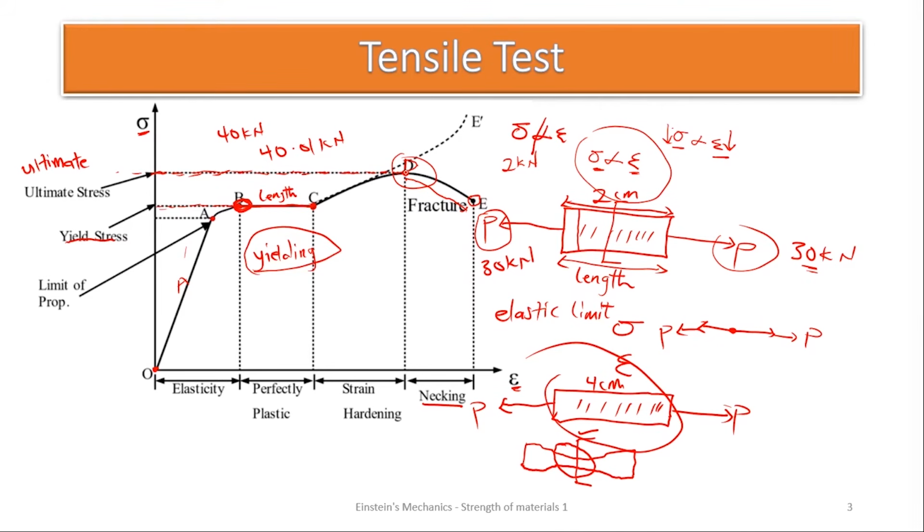Because when we read the ultimate stress, we were supposed to stop. We shouldn't have applied any other load. If it was 40, that was the strength of the material, the ultimate strength. But I decided to add a 0.1 kilonewton force to it. Then the material will start to narrow. It will start to decrease in its size, going to break.